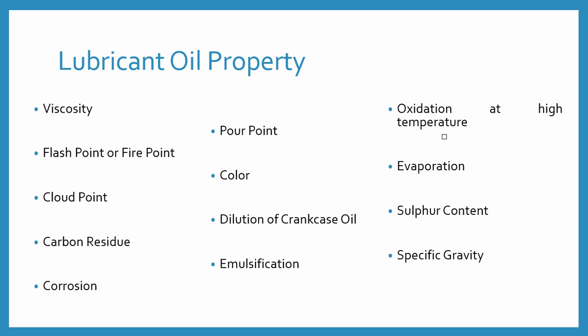Next is oxidation at high temperature. Lubricating oil may break down at high temperature due to the oxidation process, producing hard carbon and varnish which deposit on the engine parts. Therefore, the lubricants must resist oxidation.